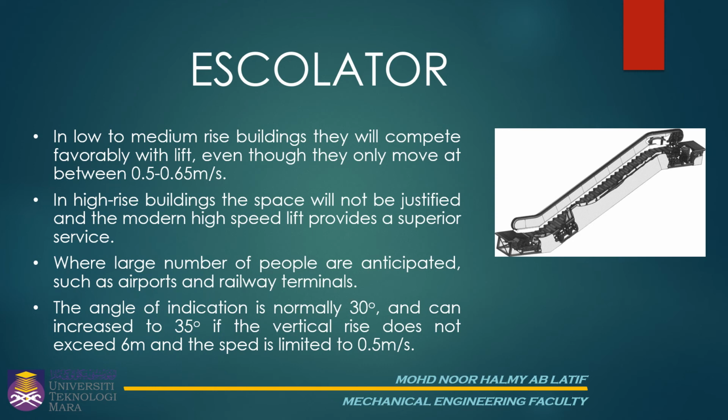Where large numbers of people are anticipated, such as airports and railway terminals, the angle of inclination is normally 30 degrees and can increase to 35 degrees if the vertical rise does not exceed 6 meters and the speed is limited to 0.5 meters per second.